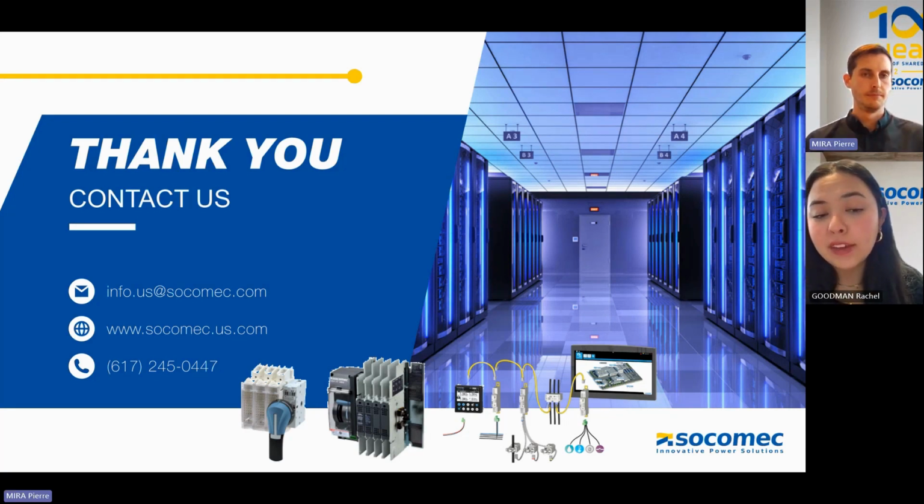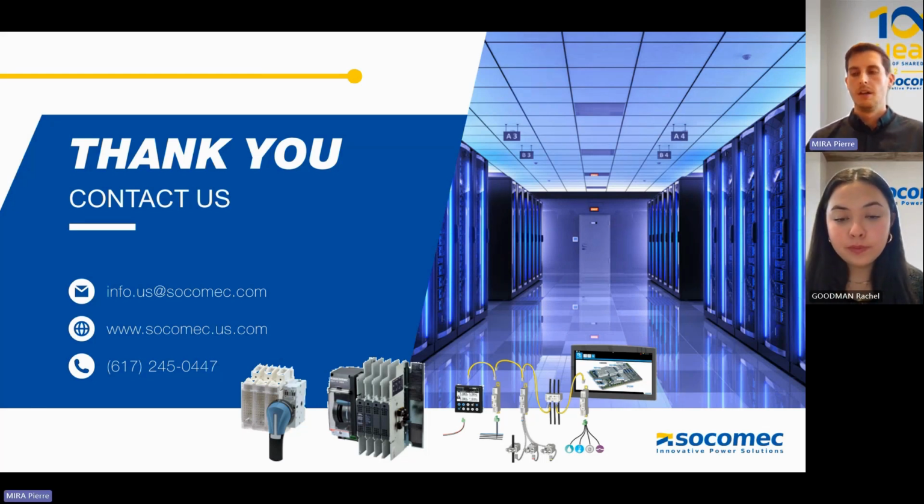Great. Another question we have is, how can a power module be serviced outside of a cabinet? As we saw in the presentation, the Socomec power module is cold swappable, patented, meaning being on bypass on the system, we can remove the power module fully safe. And at this moment, there are two possibilities. The first possibility would be to bring a factory tested power module and bring it into the system. And so at this moment, it's very fast. We don't even have to do troubleshooting of the power module on site.